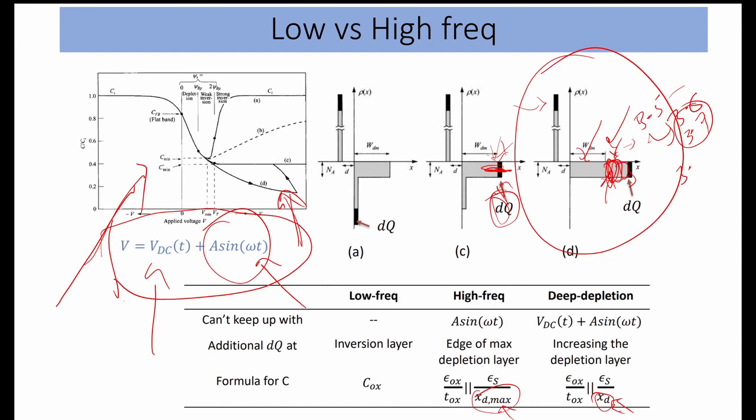If you do the CV measurements, you will get this region, and do it at low frequencies so that you can get the C minimum and see which region you are in. You can also see whether it is p type or n type. It is just flipped for the n type. If your substrate is n type, it will just get flipped, nothing else.